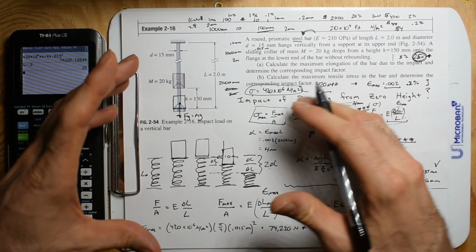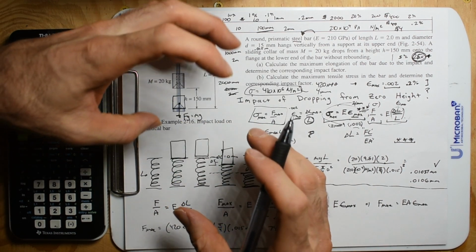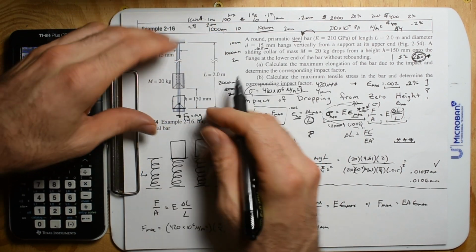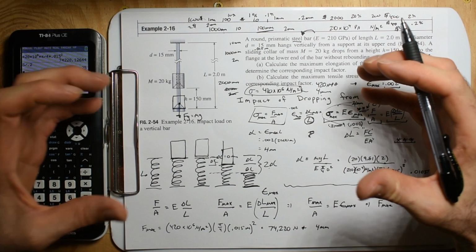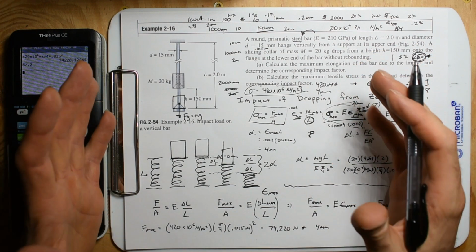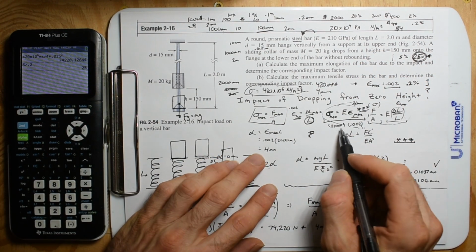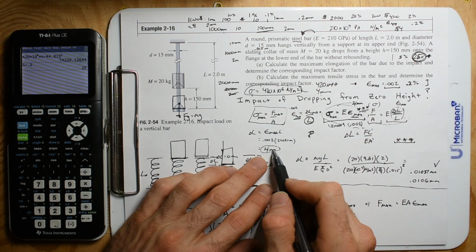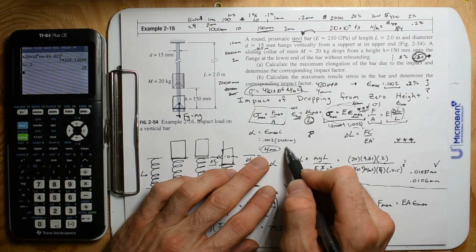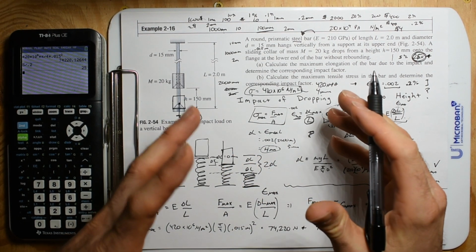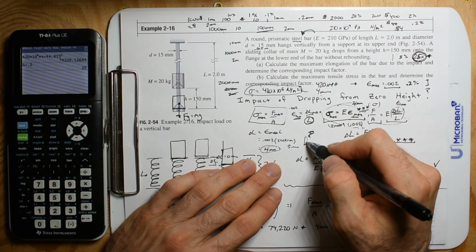Because in your fit up, if you have industrial size stuff, and this is like a two meter bar, and your fit ups aren't within a tolerance of 4 millimeters, you might put an undue 5 millimeter stretch just because one of those bars is trying to take the whole load.